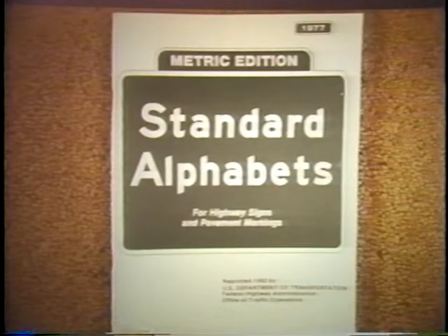The standard established for traffic control device programs defines the shape, size, and color of the signs. Standards also tell us where to place the devices, both laterally and longitudinally on the highway. These color, shape, and size standards for signs are incorporated by reference in the MUTCD, and the standard alphabets contain layouts for the letters and numbers that go on the signs, as well as pavement mark arrows, etc.